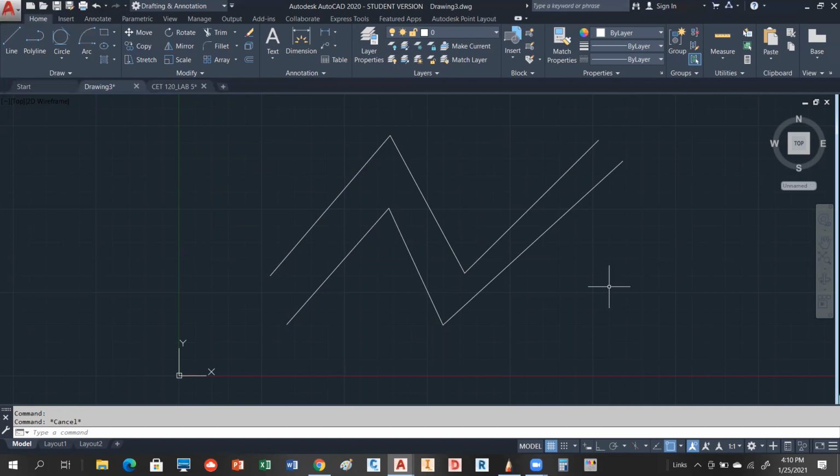I don't want to use the term thickness because thickness means something else in AutoCAD. Thickness means you're taking that object and you're pulling it out in the Z direction, making it like a panel or a piece of plywood or something. So there's a difference than that.